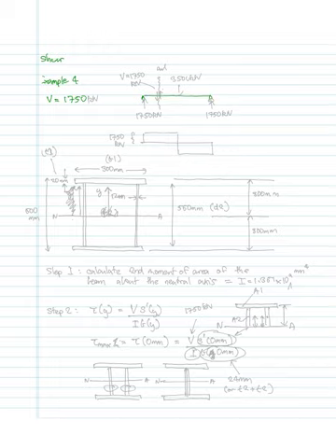If you had a simply supported beam with a point load on, then the point load would need to be twice 1750, which would be 3500, in order to lead to two reactions of 1750 kilonewtons and 1750 kilonewtons, which would then lead you to a shear force diagram something like that, where that bit there is 1750 kilonewtons.